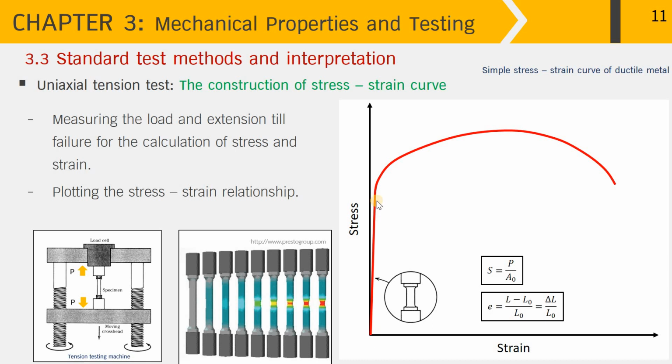And this will come within a few seconds, and then the curve approaches the yielding stage and work hardening or strain hardening until the stress reaches the maximum. And you can see that the gauge length of the specimen is still extended uniformly till reaching the maximum point of the stress, and this point is very important.